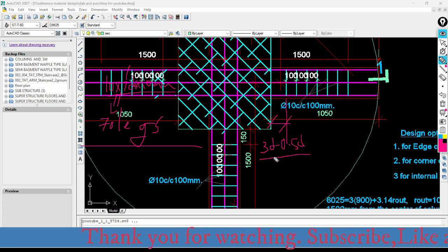This is provided in the code. We have already provided a spacing of 10 centimeter, so I can place the rebar ties at every 10 centimeter. Here the first one, the second, the third, the fourth, the fifth, the sixth, and the seventh.